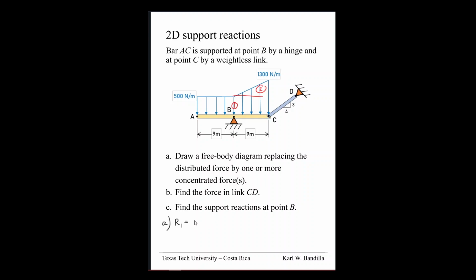That would be 500 newton per meter times 18 meters, 9 plus minus 9. That gives me 9,000 newton, so 9 kilonewton. And where is it going to act?